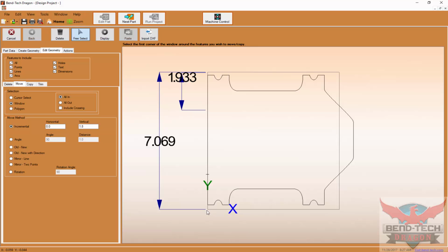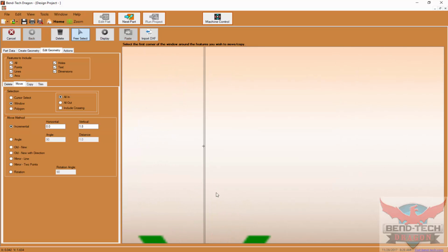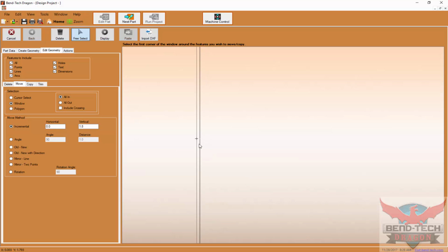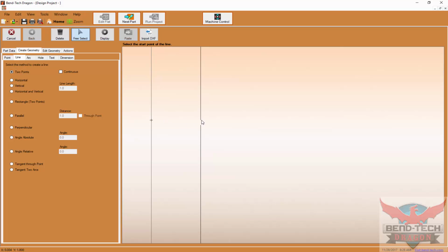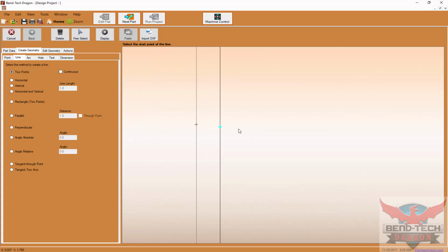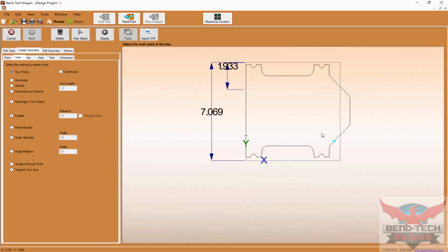here and here. So if you consider this entire vertical axis your circumference, we just want to make sure that these notches on the ends of the bump stop can are within those bounds. Then if we zoom in close to where we connected these two pieces, we might see a break in this case here, and we're just going to go ahead and fill that break in using create geometry line. Make sure you're not in free select mode, then it'll snap to those points. Quick fix that.